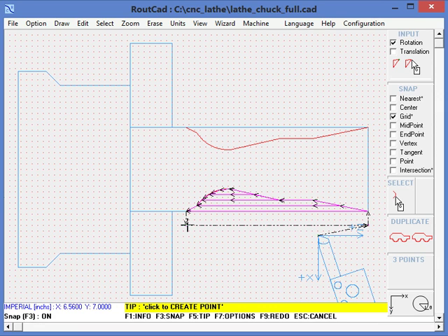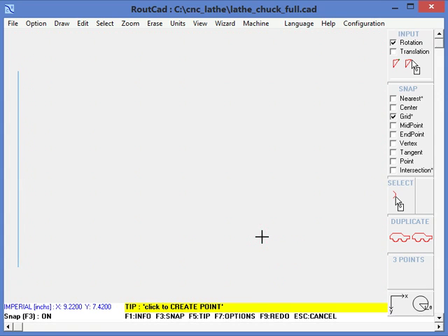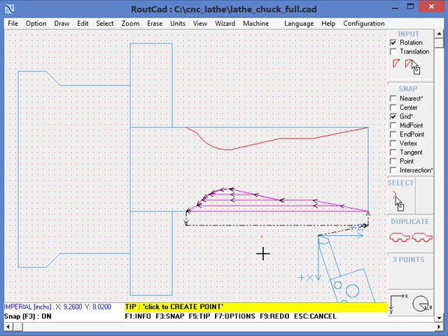Now we will put some other location that we want the CNC to go to. The other location is, for example, a location over here. So we're going to click a point over here. We would like the CNC to go to another point. There's already a point here, but we will add another point at this location over here. So we click on it. So we have one point over here, one point over here. Now, if we do nothing, nothing will happen. The CNC will just machine the surface of revolution and stop over here. But what we want is the CNC to go to this point.